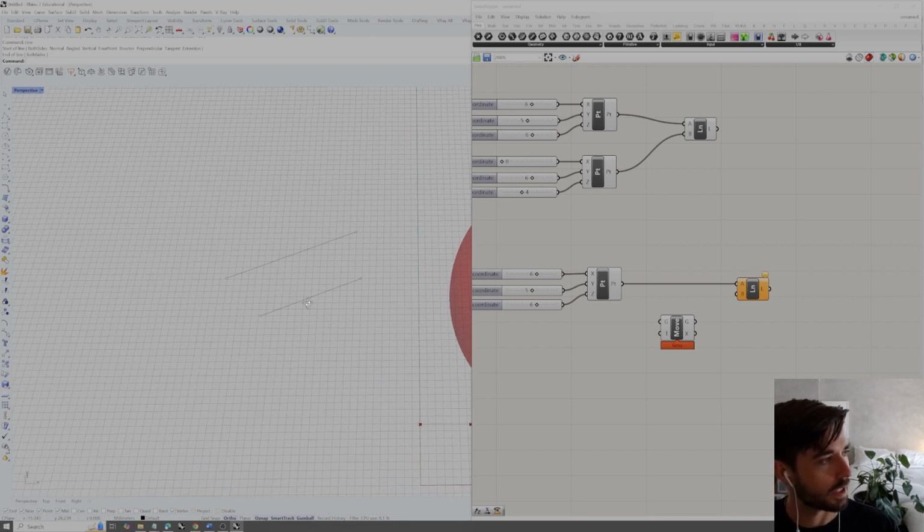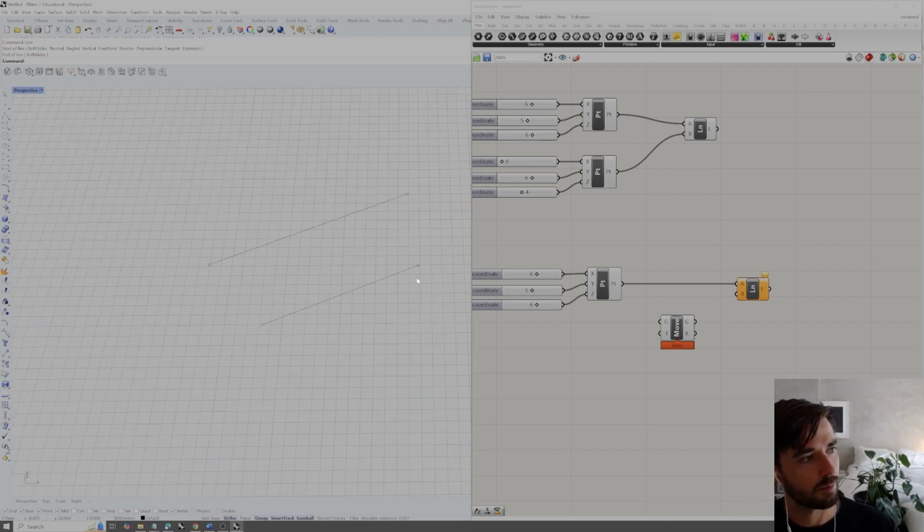If we wanted to move it instead, whatever this set movement that we've placed here is, we would want to first understand what this vector is. So what we need to do is determine what vector would get us from this starting point to this endpoint. We can do this by checking the x dimension, so drawing a line just in the x-axis here. And I'm using my smart track to be able to draw to that intersection. And then we can select that line and type length. And this gives us the length of the line, which is 13.577 millimeters.